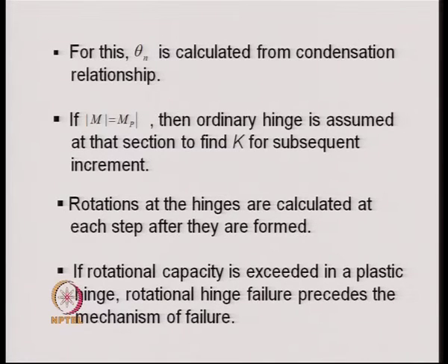Also, during the calculation we go on calculating the rotations at the hinges, or the plastic hinges. Even if we assume an ordinary hinge at the time of the analysis for the cases where the section has yielded and the moment is equal to the plastic moment, after the analysis is performed we find out the incremental rotation also for the ordinary hinge.